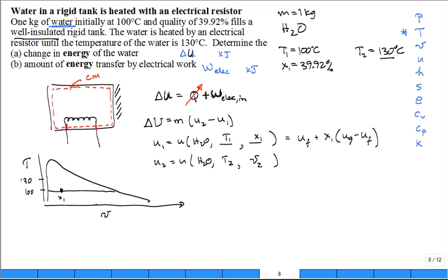All right, so you can find V2, that's equal to V1. How did you find V1? You just use the same type of equation to get V1. It's going to be V sub F at 1 plus the quality at 1 times V sub G minus V sub F. That makes sense? Thumbs up? You're following me?